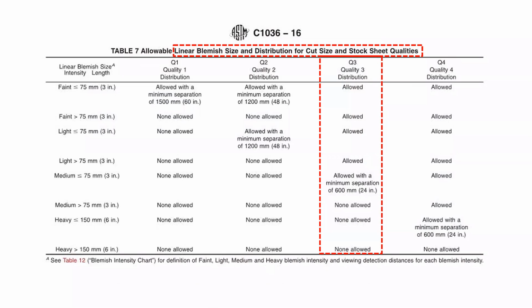So these would be scratches. Again, we'd like to point out that for the light intensity viewing distance, something that you can first observe very close to the glass, like 8 inches away, if that's the first time you can observe these blemishes, you can have scratches up to 3 inches long at that point, and they're still allowed.